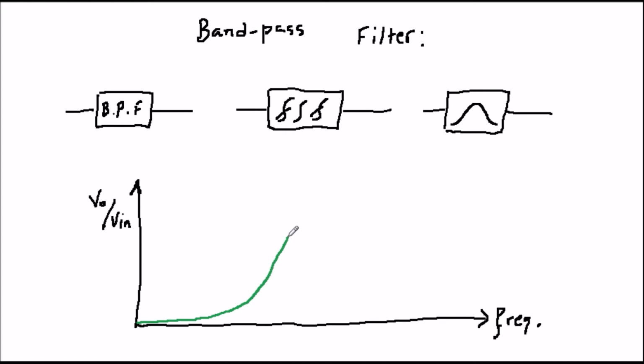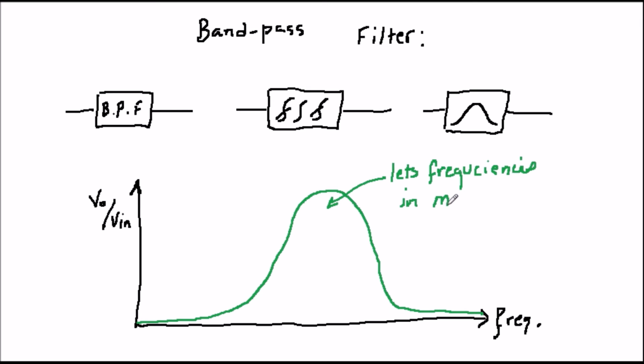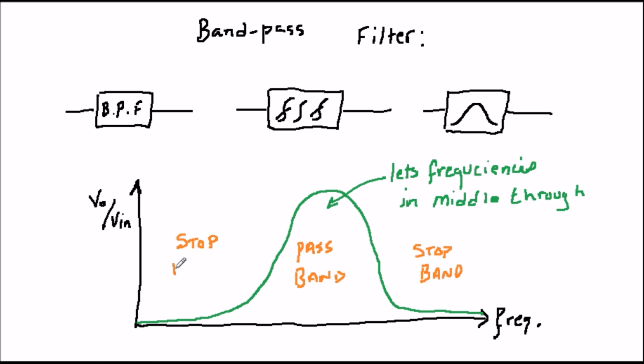The third type is the band-pass filter. This rejects both high and low frequencies but allows ones in the middle to pass through. The tuning control of a radio, which we described previously, is an example of this. It only allows a wanted radio station frequency to pass and rejects all the others. Bandpass filters can be made by combining low-pass and high-pass types.